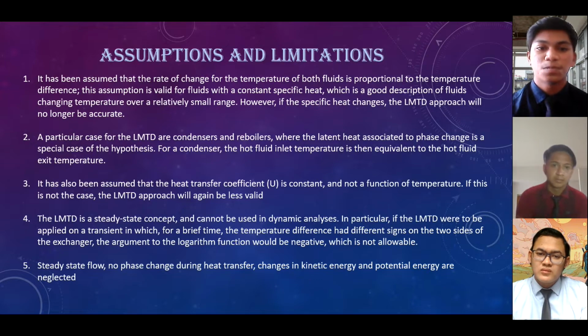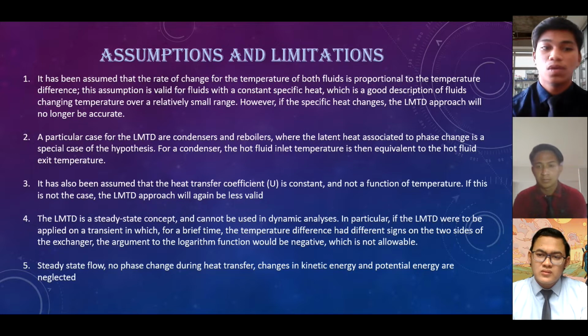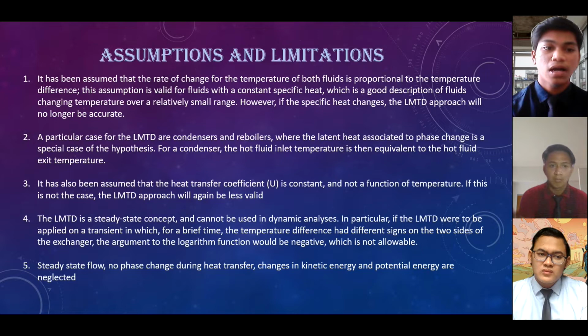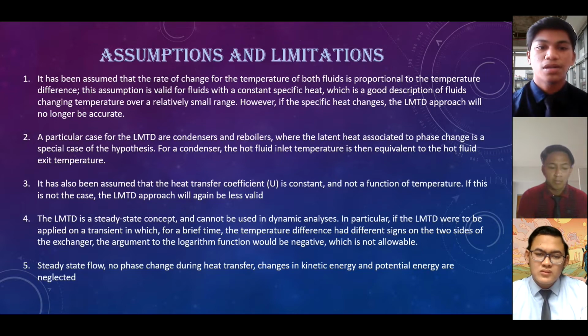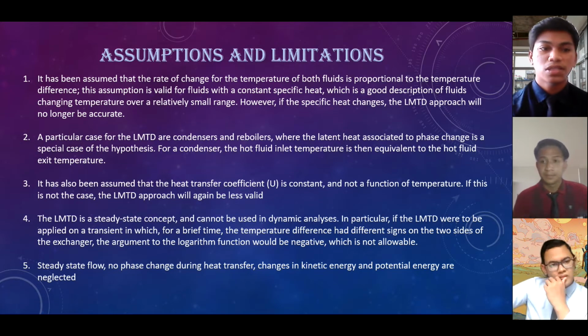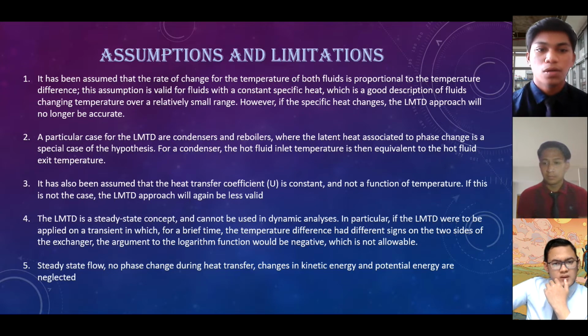However, if the specific heat changes, the LMTD approach will no longer be accurate. Secondly, a particular case for the LMTD is the condenser and reboiler, where the latent heat associated with phase change is a special case of the hypothesis.